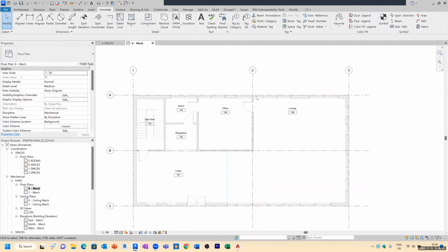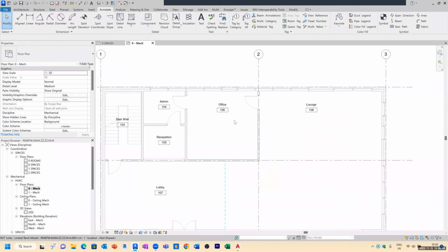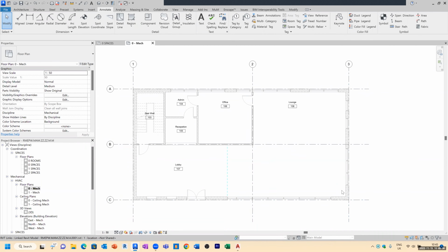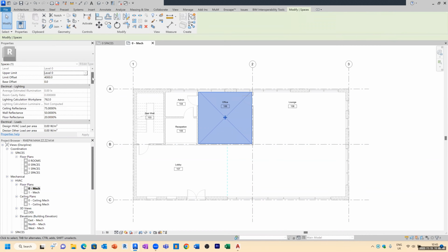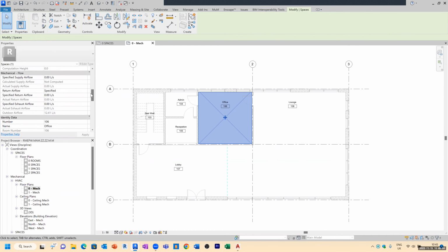So we're going to add some ventilation grills in here now, some supply grills, and we're going to come up in the corner of the office space with our supply. So the supply is going to come down the building and feed into some of these grills. So taking the office as an example, I'm not quite sure why we've not got any flow rates in here, but let's add some in. So let's just say we need 160 litres a second of supply air into this office space.